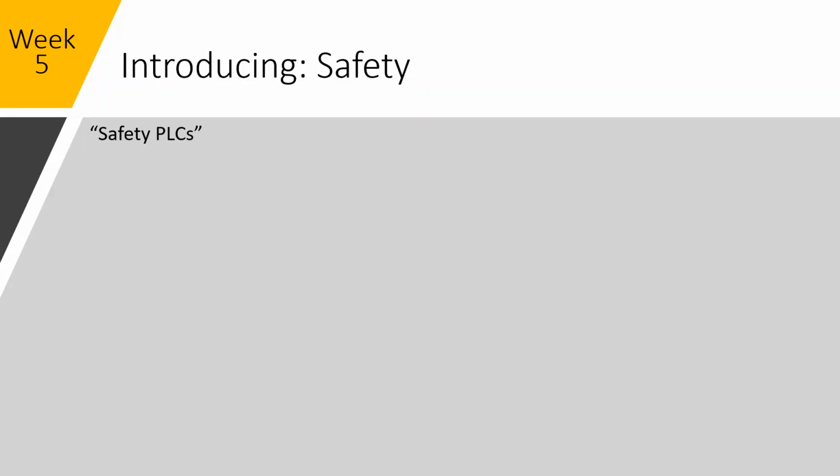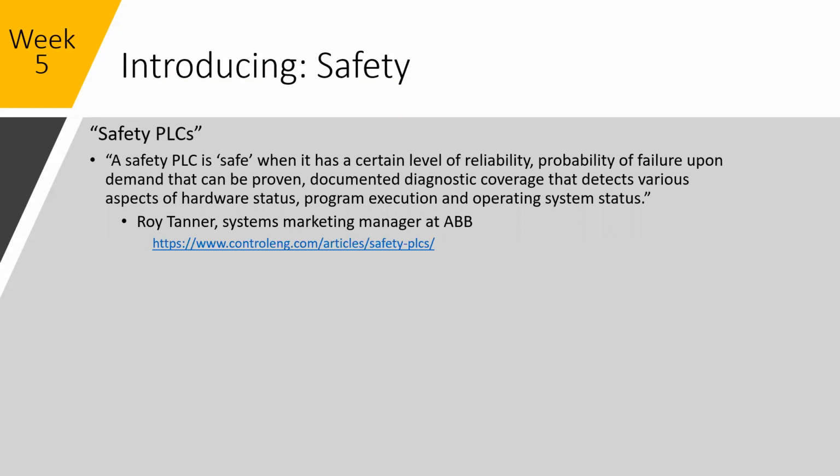So safety PLCs. There's a quote here from Roy Tanner, the marketing manager at ABB. A safety PLC is safe when it has a certain level of reliability, probability of failure upon demand that can be proven, documented diagnostics coverage that detect various aspects of the hardware status and programming execution and operating status, system status.